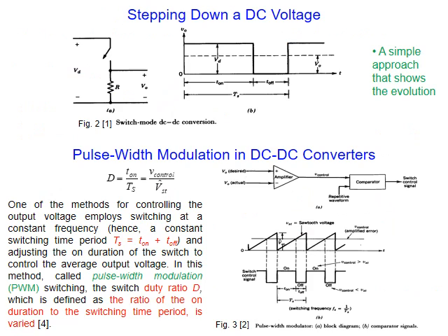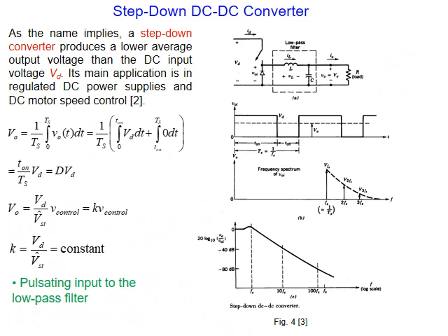This one here is a switch with load, but what we are going to do, we improve the same circuit here by putting a diode because we want a freewheeling diode. We want another path for the energy released from the inductance.